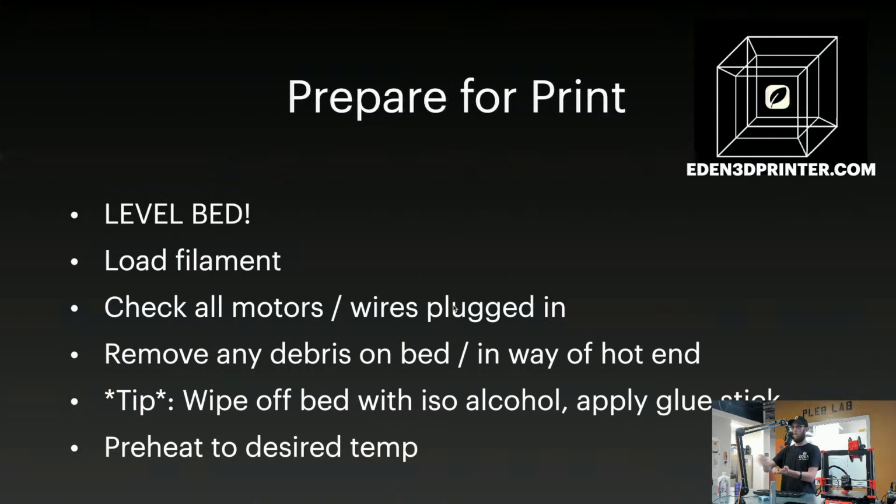Glue stick. Just regular, not Elmer's glue, a regular good old glue stick works wonders. I don't have any up here at the moment, but that works wonders to help it stick better. Again, make sure your motors are all plugged in and checked fine. I've had issues where the motor was not plugged in. It just rattled my brain for a day or so.